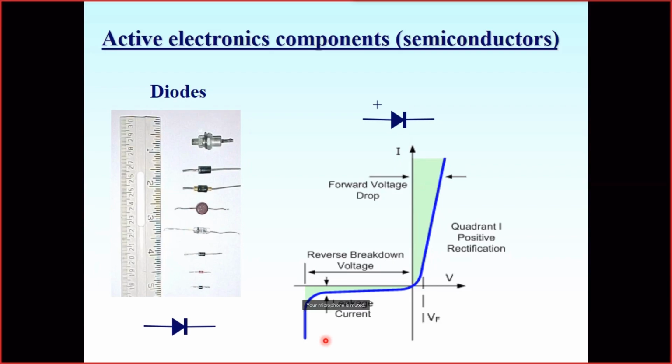Another thing, which is not mentioned here but we should remember, is that diodes always have some parasitic capacitance that can be modeled as a capacitor switched in parallel to the diode. The capacity is higher at reverse voltage, and it's related to the distribution of the charge in the PN junction, but the capacity is always there.